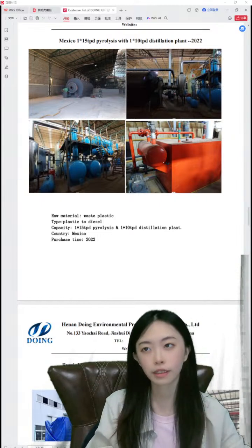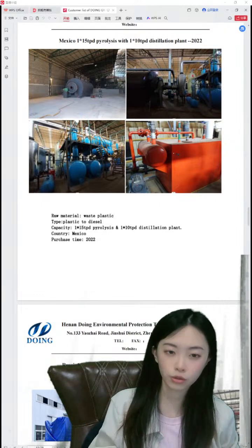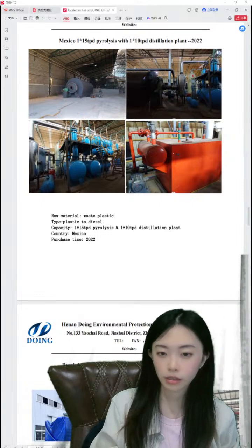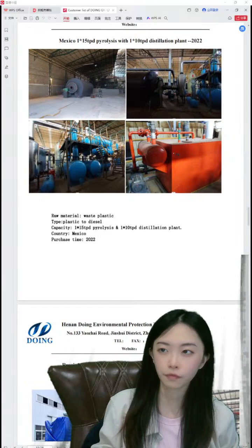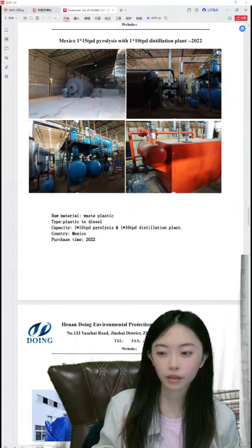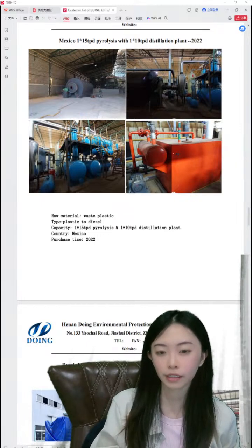We have this vacuum safety device to ensure there's no oil gas, flue gas or tail gas in the reactor after the pyrolysis process, because when an explosion happens, it is because some remaining gas is in it, and when we open it, the high temperature causes a sudden explosion.